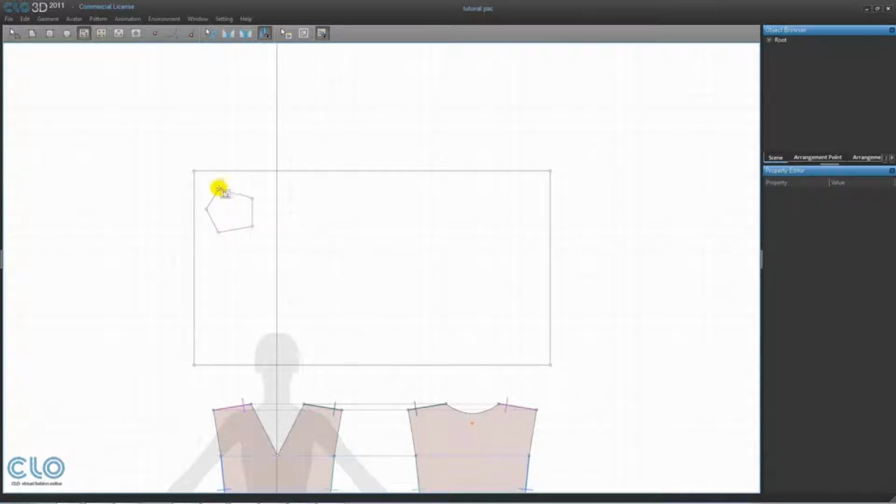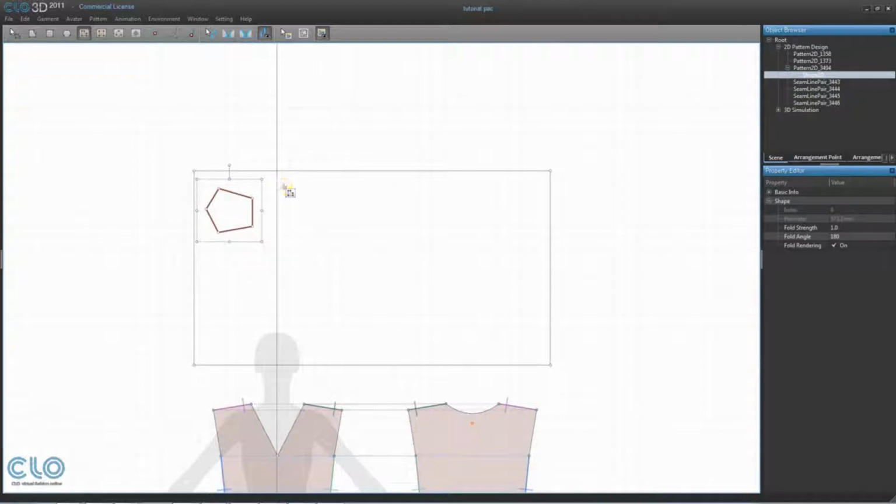You can click points to make an internal polygon by using the Create Internal Polygon tool, and hold down the Control key to create curves along the way. Unlike the regular pattern tools, which have to exist as closed-off shapes, the internal pattern tools can be drawn as segments and polylines. After you are finished clicking lines, simply re-click the last point to complete the polyline.